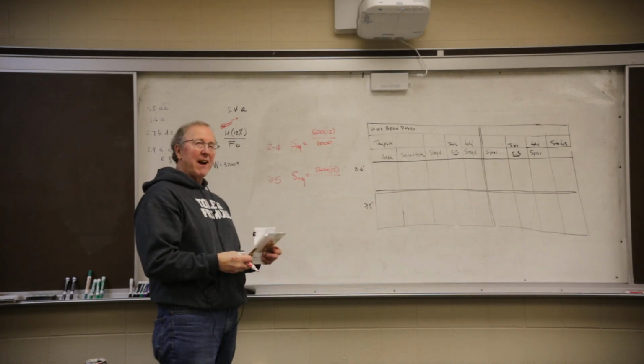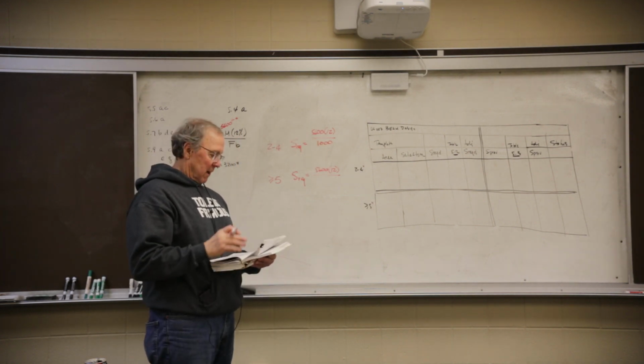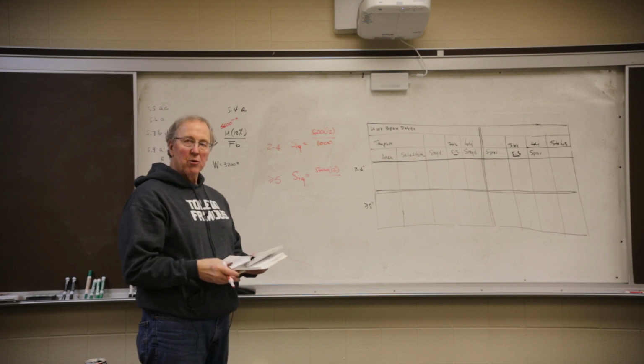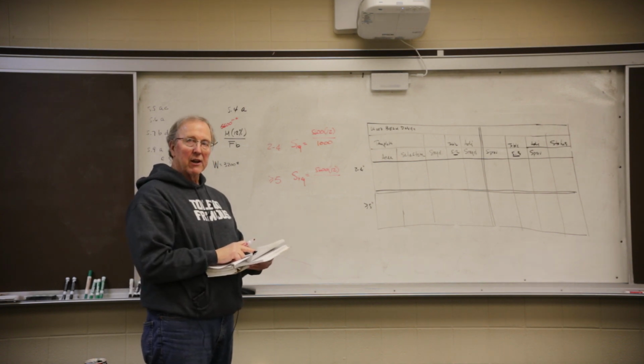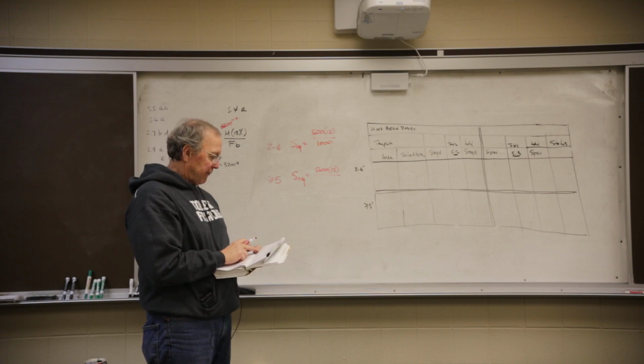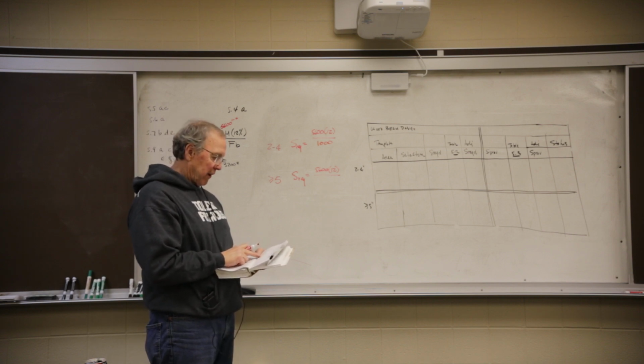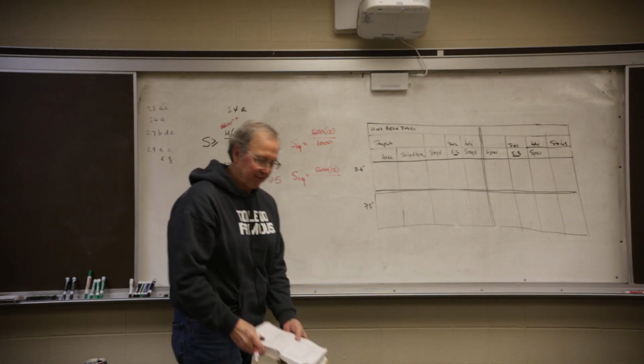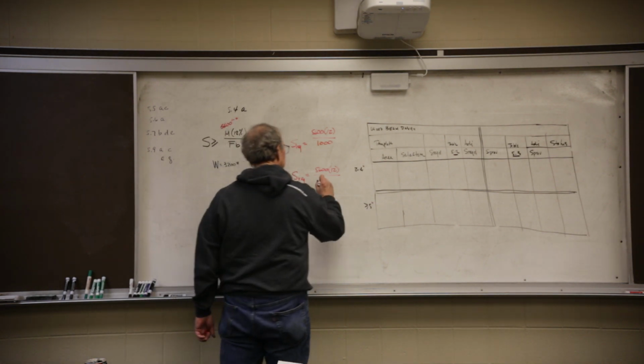Now, if it's 2 to 4, it's 1,000. How about if it's 5 or greater? Okay, go to cell 2. Y2, it's a beam, and it's fatter than 4. Okay? Put your finger on number 1 grade, go over to that first column, and I think you're going to hit 1350. 1350 goes here.